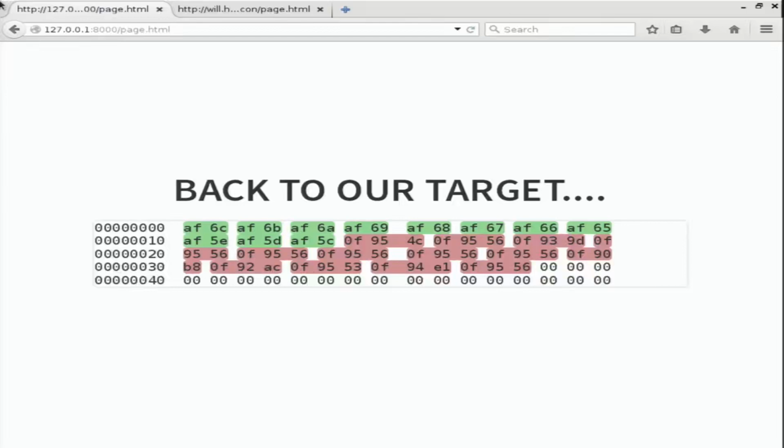So let's think about what we know about vector tables. Well, if it's addresses, probably doesn't make sense. We'll just look at the first part. Because if we look at those as big endian encoded addresses, well, they only differ by a single byte for each value, so that can't be branching to meaningful code. Or if it's a little endian encoded address, then they're spaced by 0x100, or 256 bytes, and then it runs off the size of the module we just loaded, so that can't be a sensible explanation either. And that leaves instructions for the other option.